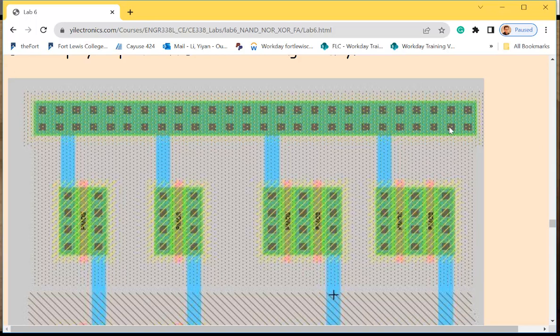So on the top, is that an N-type or P-type? What? I'm not saying TYP, I'm saying TAP. Yeah. Is that an N-tap or P-tap? So think about tap, it's just a, make a contact or touch. You know what I mean? And is this one an N-type or P-type? So the squares are vias, right? No issues on that.